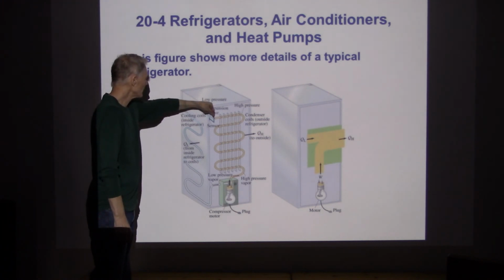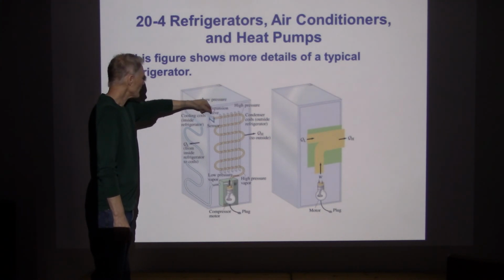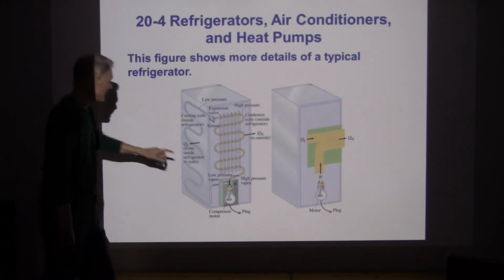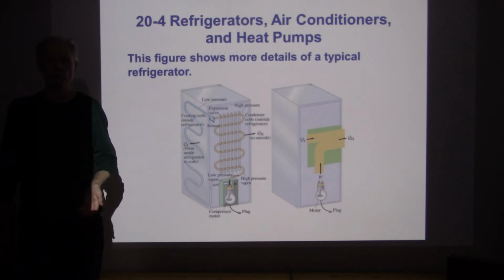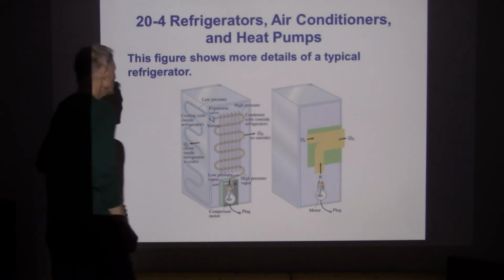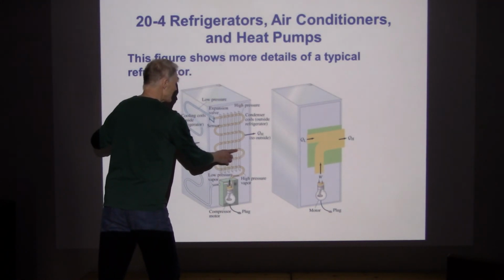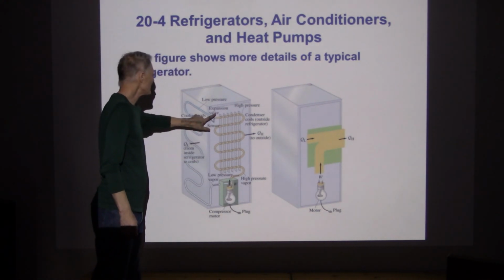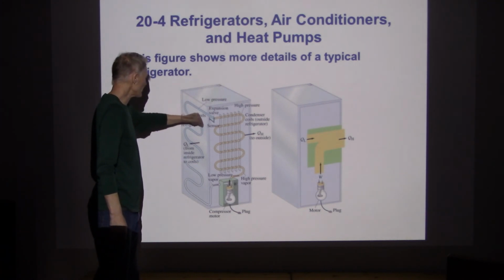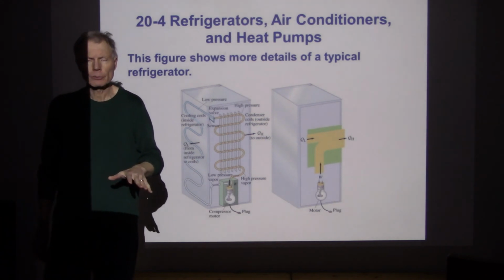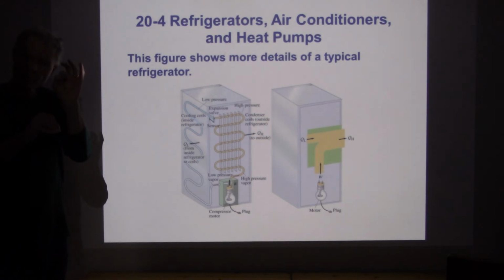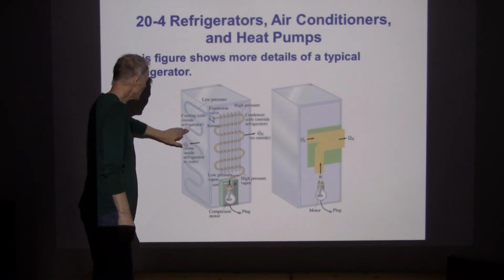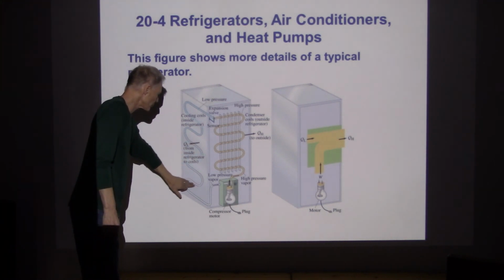And then on the other side of that valve, it cools down. They say vapor still, so you can have phase changes taking place in these coolants also. So there's a high pressure, high temperature region maintained by the compressor, and then this valve creates on the opposite side a cold region. The coolant, released through this valve, drops in temperature dramatically, and as it makes its way through, it draws thermal energy from inside the refrigerator.